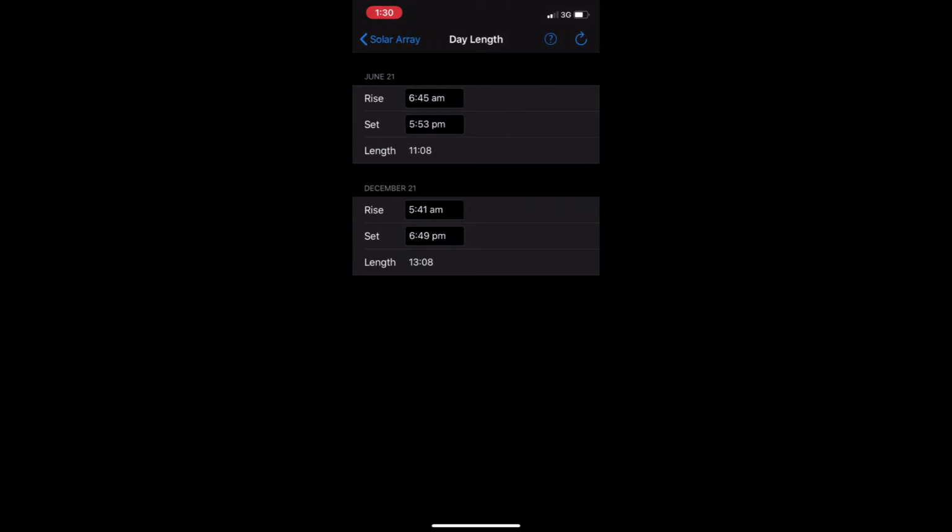The purpose of this screen is to fine-tune the day length of our installation site. If there are trees, landforms or buildings that cause shading of the panels, then that can be accounted for here. Important to note that you don't need to account for any shading that occurs from your solar panel orientation, east, west and their tilt. That is all taken care of by the scientific modelling.